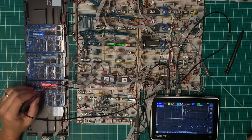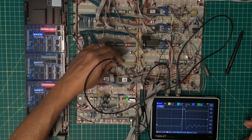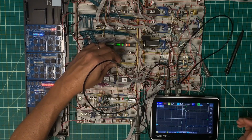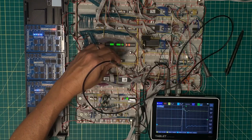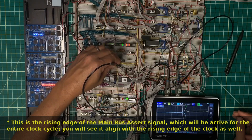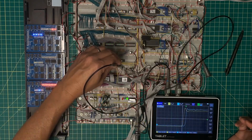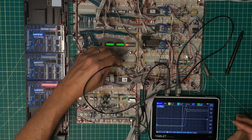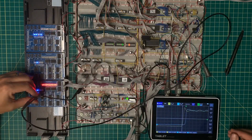The other one I want to measure is the fetch register assert, and that should be there. And again, that looks good as far as the shape of the signal is concerned, and the delay itself looks consistent. Now, if I go to the rising edge when it's deasserting off the bus, this is going to take a minute because it's got to re-average. But once again, the shape of the signal looks pretty good. I'm at 50 nanoseconds per division. It looks consistent. And if I hop over here, again, that looks quite reasonable.